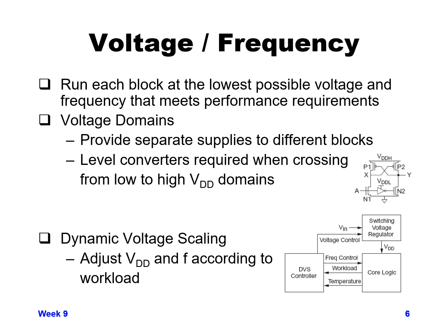So you do need to keep in mind that every signal that crosses voltage domains, you might need these level shifters, and potentially even another circuit device that's called an isolation device, where if one voltage domain actually goes down to zero, like if you disable that voltage domain because you know the logic that's in that domain isn't being used at a given period of time, you might want to turn off the voltage completely to eliminate both dynamic power and static power through leakage.